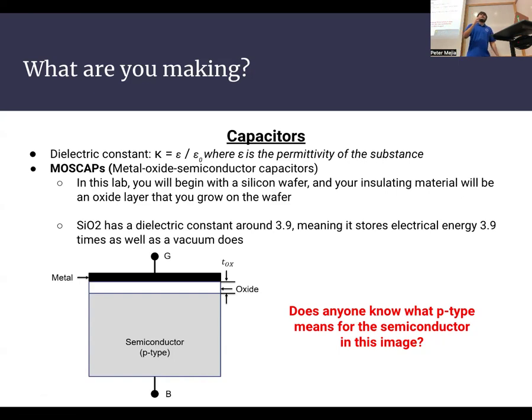So say we have silicon, which has 4 valence electrons. How would you get a p-type, meaning you have a positive charge associated with it as a charge carrier? Something with fewer valence electrons, so it's to the left of it on the periodic table. Exactly. A common p-type dopant would be boron, because boron has 3 valence electrons. On the periodic table you'd see boron, then silicon, then phosphorus. So for p-type, you use boron because it has 1 fewer valence electron than silicon.